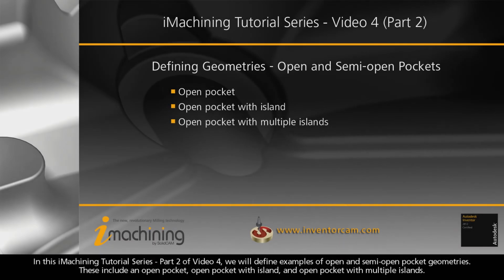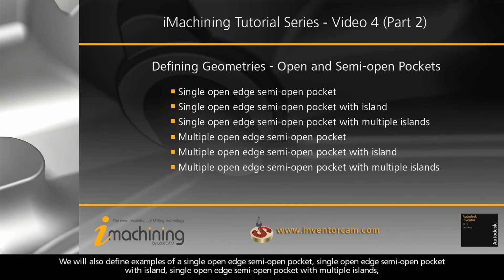In this iMachining tutorial series, part 2 of video 4, we will define examples of open and semi-open pocket geometries. These include an open pocket with island, and open pocket with multiple islands. We will also define examples of a single open edge semi-open pocket, single open edge semi-open pocket with island, single